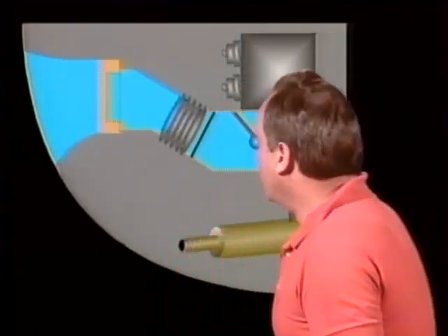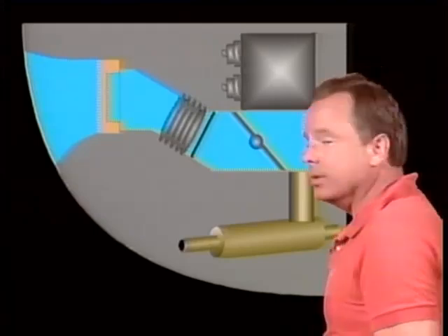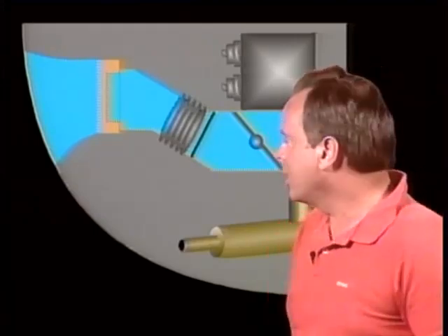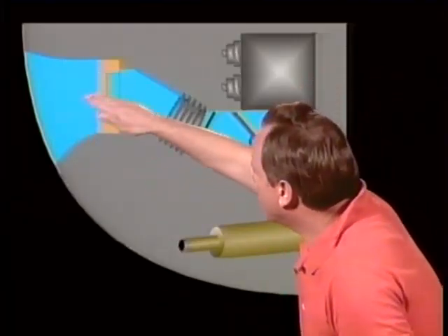Now, let's assume you want to start this engine and it's equipped with a carburetor air heater. Should you start the engine with the carburetor heat in a hot or cold position? Well, the answer is anytime you're operating on the ground, you want the carburetor heat in the cold position so that you have filtered air going to the engine. Otherwise, the air is unfiltered. So you start the engine, operate it on the ground with the carburetor heat in the cold position.